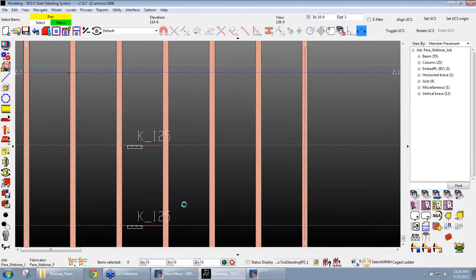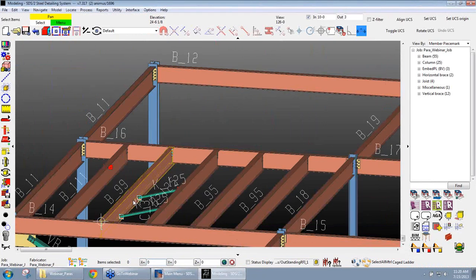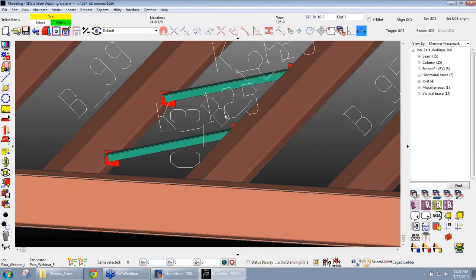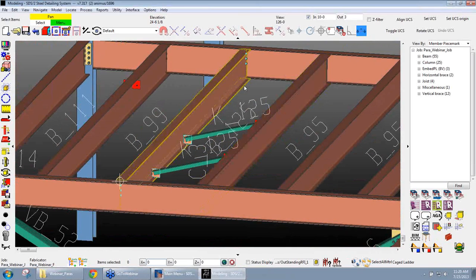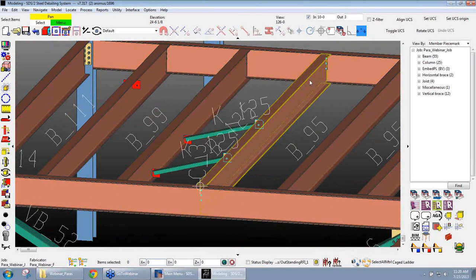Go through and process and create solids. And there I can see now I've got a couple kicker angles quickly modeled in there. I could have gone farther down that line as needed, or I could have reversed the points that I selected, point 1 being here and point 2 being over here, to reverse the high and low sides on those.